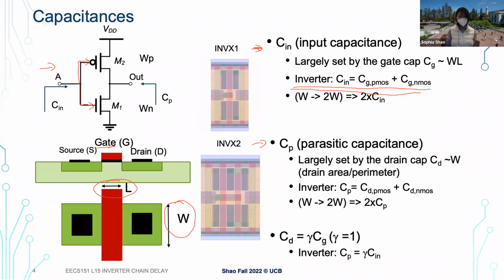So now when we come to the dimensions, we talk about how we can have a bigger drive, or a bigger transistor. Typically, we don't modulate the length. We mentioned that's basically the feature size, dictated by the technology roadmap, right? All those different nanometer technologies, that's basically the length of the gate, the length of the channel. What we can do from a circuit and fabrication perspective is make things wider. We can have bigger channels, so that the current can flow through a wider channel and flow faster, right?